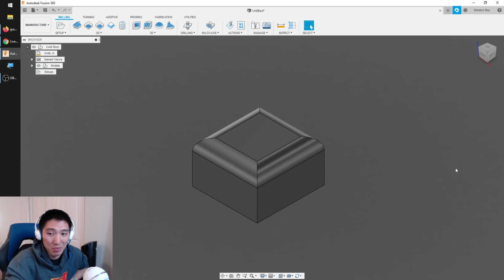Have I fallen in love with 3D printing yet? Not really, kind of, but no. It's a good means to an end, but it's not something I choose to do just for fun. I use it because I need to, because there are some cases where 3D printing is the best way to come up with a geometry, particularly if the box dimension of your part is like 90% empty space. There's not much of a reason to machine away 90% of the material just to be left with a shell or a U channel or something like that.